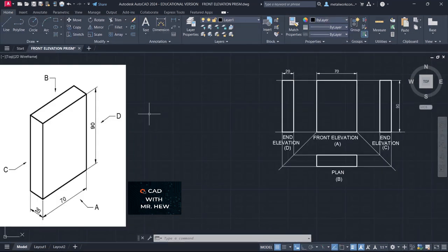But there are two construction lines that we need to put on the drawing, right? Especially if you're drawing with a traditional instrument. So we're going to turn on object snap. We have to carry down this line coming down here to meet the plan right here. Enter. We have to carry enter to get the last command. We have to carry down this point here to meet that point. Press enter. Right? And this would have been the complete construction lines that are required for the drawing, okay?